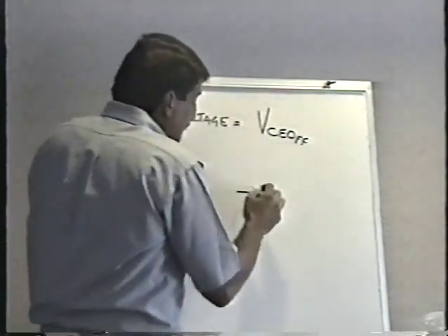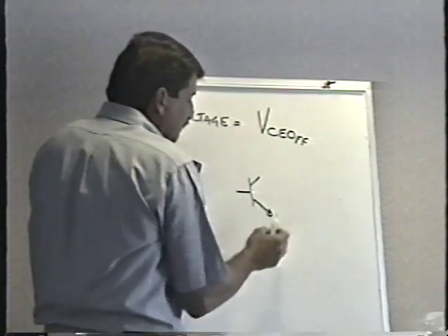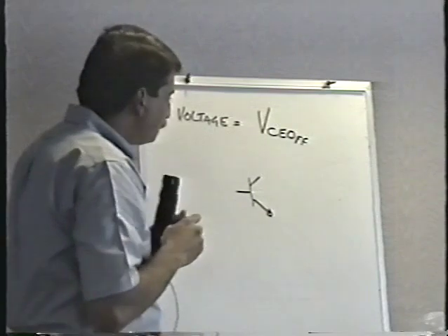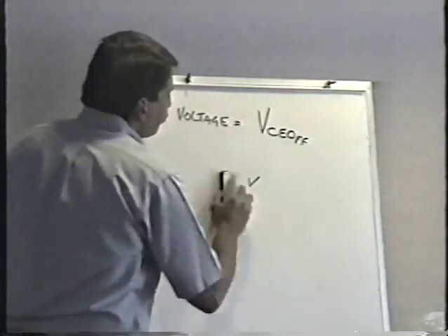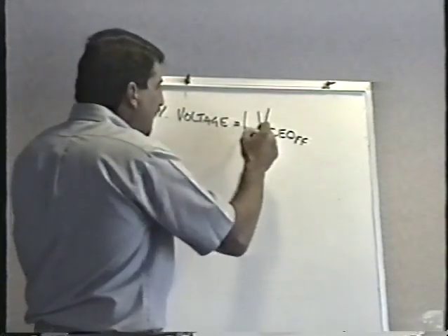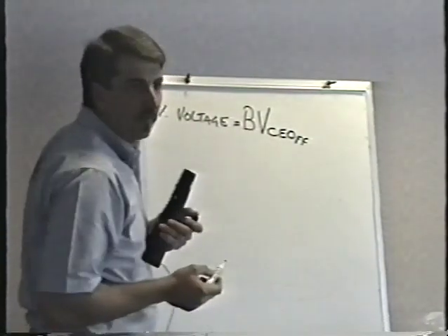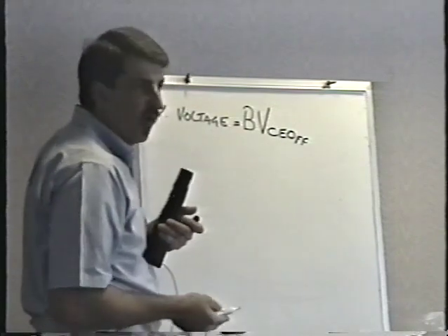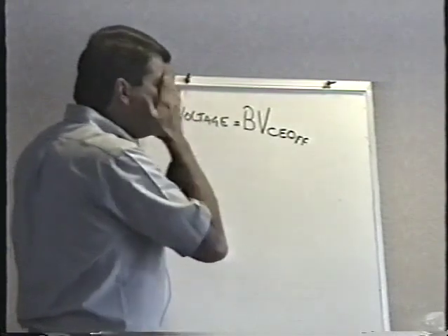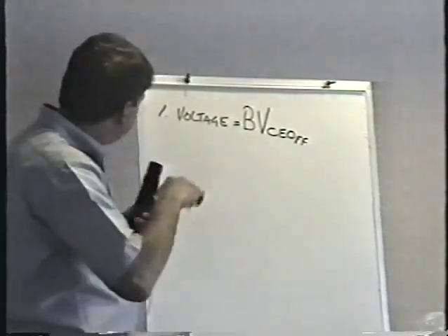But of course, that's when the transistor is blocking the voltage, isn't it? When it's turned off, that's when it's blocking it and it's not allowing it to flow. Sometimes you'll see this listed as BV for breakdown voltage. V sub CEO, BV sub CEO, same thing. This is the voltage rating, the main voltage rating of the transistor.